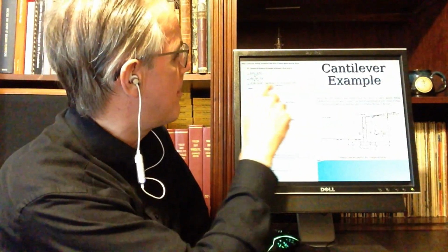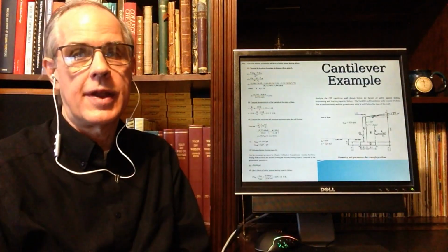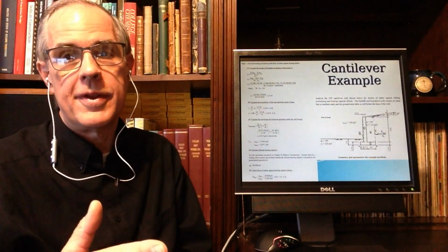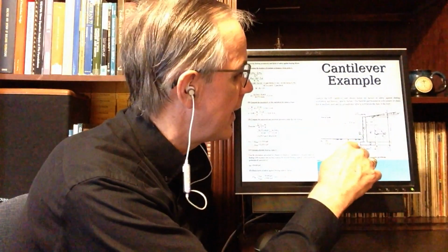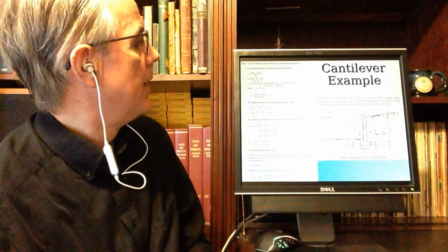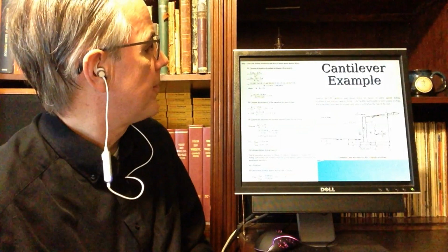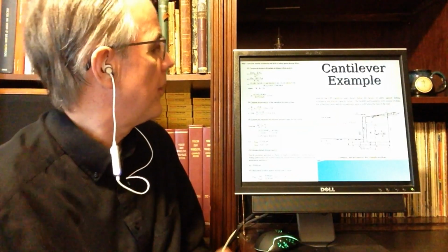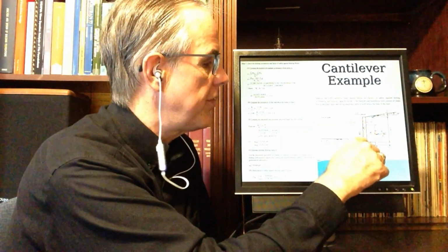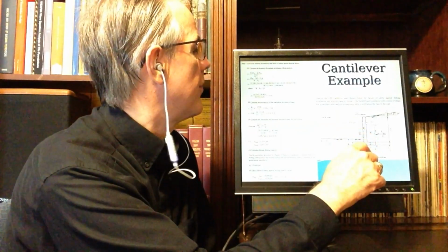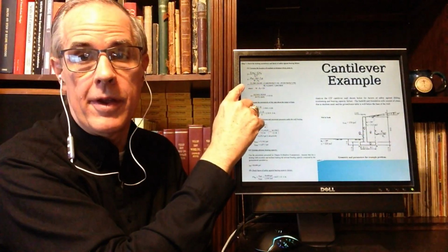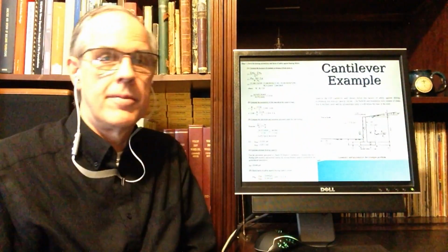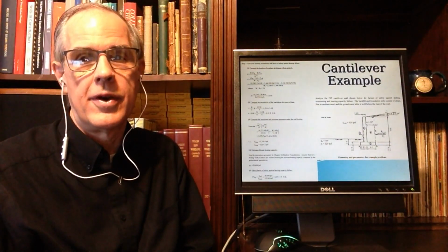You can trace these back through your problem to where they came from. The resisting moments minus overturning moments is the net moment at this point right here, point A. Then you divide this by the resultant of the vertical forces, which is why they have the summation of V, and you will get a moment arm. That's what you're aiming for here.